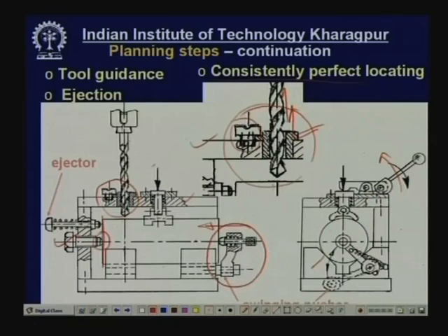This is called a pusher. Now, if you just push this pin out against the spring, there will be contact. If you release it, then under the action of the spring, this pin will apply a small force on the rod against this locating pin. So, this will assure absolute contact, and after it is fitted in, then clamping and other things will be done.